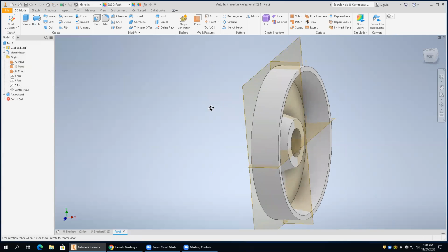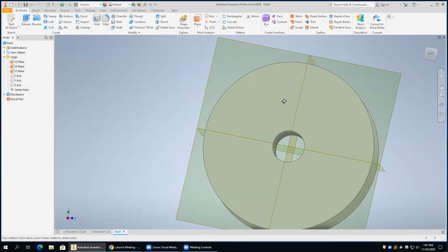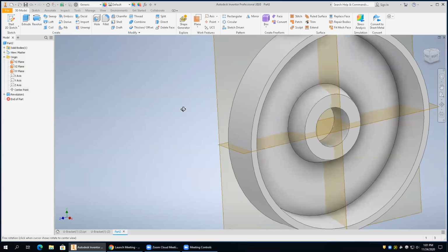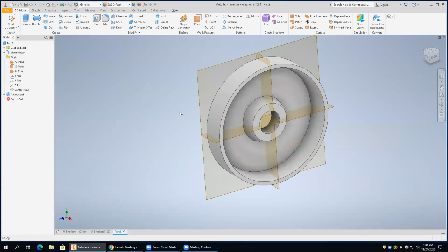And if you look at this thing now, you'll see what you've done is you've generated a pulley. Notice the 2 sides. One is like that, and the other one is like that. You can use that revolve tool for a whole lot of things. So you can just draw a path curve and revolve it about an axis. It's really a pretty cool tool.